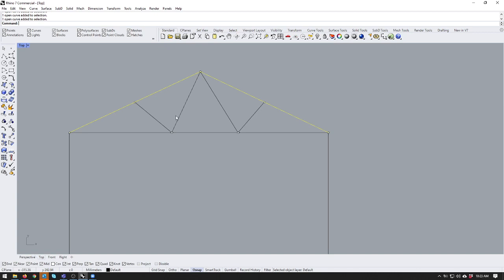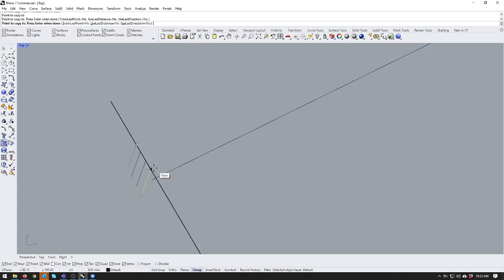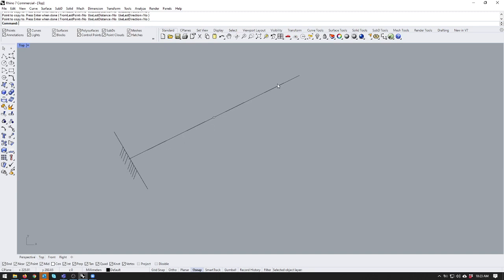No, but look, let's think about this for a moment. If I draw a single beam and I put a joint in the middle of it, that joint could be any type of joint. I'll make this a support. So I've got a beam, I put a joint there. Now, when we talk about the joints that we were dealing with last week and the week before, we've got rigid joints and pin joints, right? Those are 2 of the more common joints that we can see. We also see movement joints and various other ones, but the more common ones are rigid and pin.